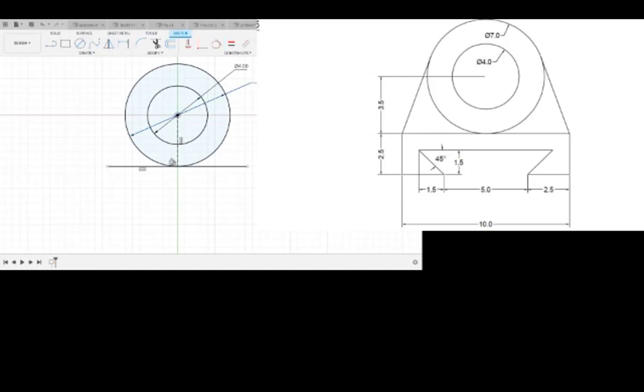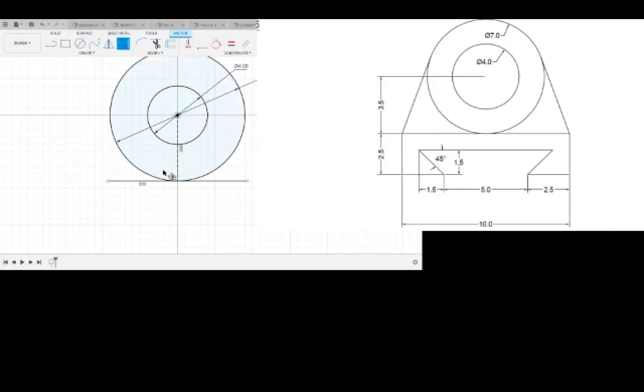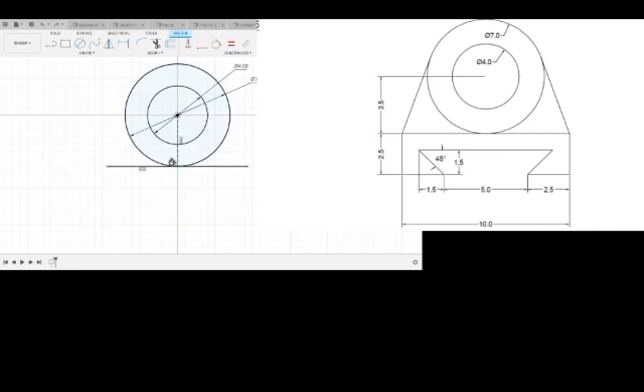So say if I want to change the radius of this, or the diameter from 7 to say 9, the line goes with it because it's tangent to the circle. Whereas if we deleted the tangency constraint, and then set this just to be the same length and made it 3.5, and then change the value, it doesn't go with it, because now it's not geometrically constrained to the shape, but it's simply numerically constrained via distance. There's another little nice trick.